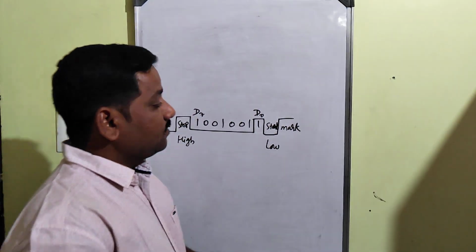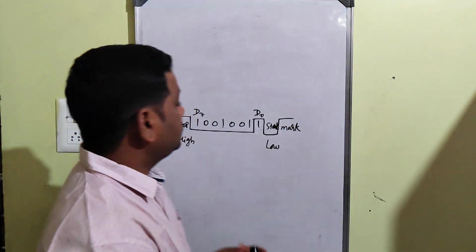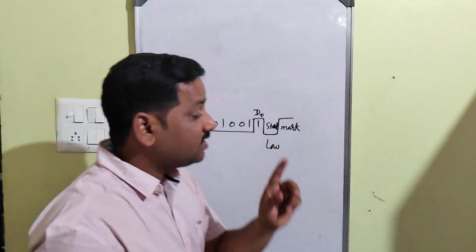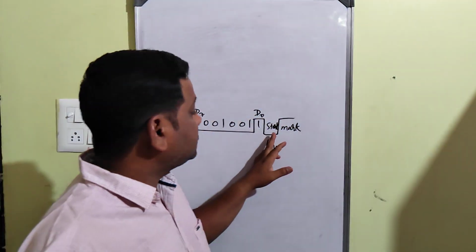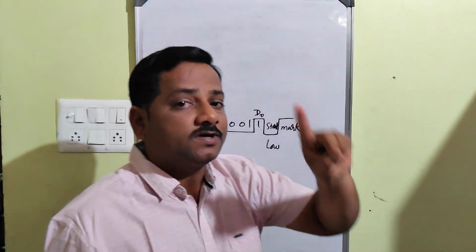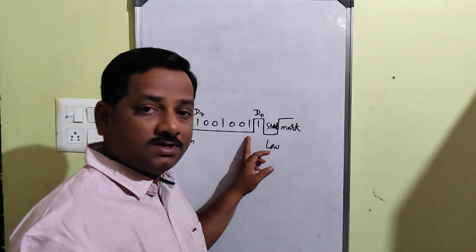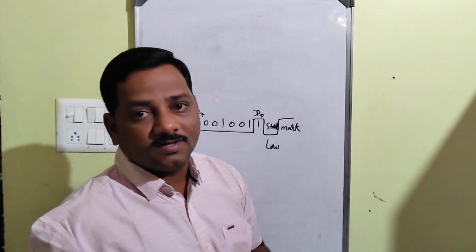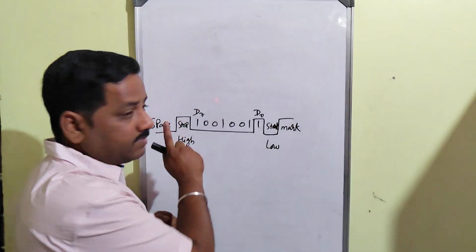Okay. So when we transfer the data, first we will have a start bit. Okay. Receiver will receive the start bit. When the receiver receives the start bit, he understands that okay, we are going to receive 8 bits now. So after that start bit, the LSB will be transferred first. Okay, then next one, next. So after receiving the D7, that is the 8th bit, the receiver will receive the stop bit.